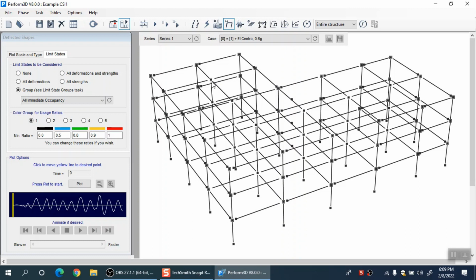Generally in CSI ETABS there is a lumped mass approach used at each node. So if there is a beam with 2 nodes, the program lumps half of the mass at one node, half at the other node, right. So it has two lumped masses at these two ends, and those actually contribute to the M matrix if you don't go for that lumped story approach, right.